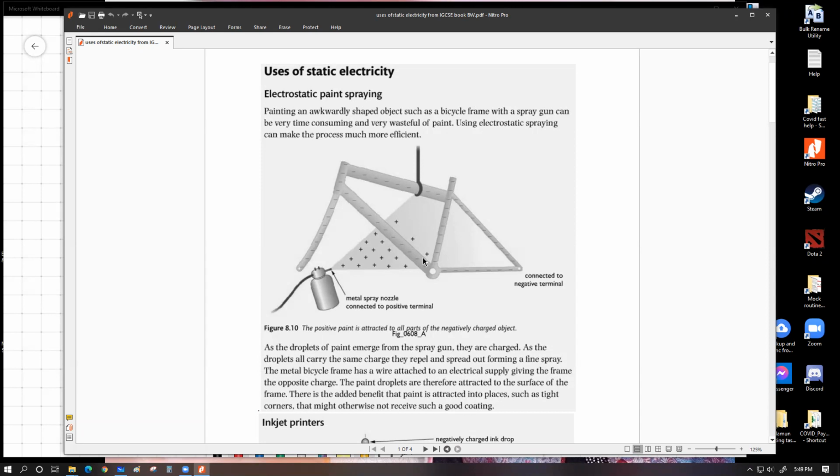And how do we prevent that? In the first place, we prevent it by rotating this frame and maybe also rotating the nozzle spray in different locations, which can be programmed by a computer or done by experienced painting people. They have to wear proper goggles so that they don't inhale those charged particles. But we do not ever do over painting in a spray painting process. The entire idea of spray painting is that we essentially apply the exact amount of paint required for the object, while maintaining a uniform thickness everywhere.